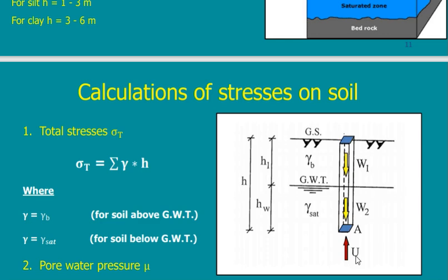Of course, water pushes not only up. What is important about water is that the stresses in water act in all directions. If I am standing at a point inside the water, water can push to the right, to the left, up, down, all with the same value. It is isotropic. In any direction, the stress can be applied. So one of the directions of application is up, so water can push anything above it.